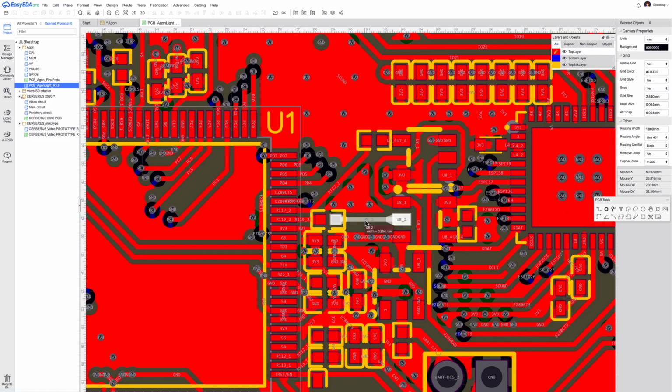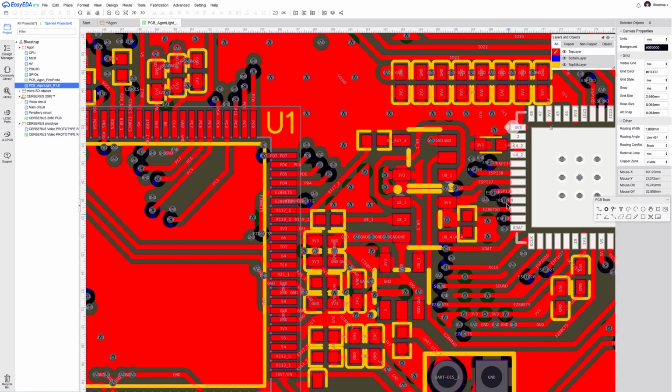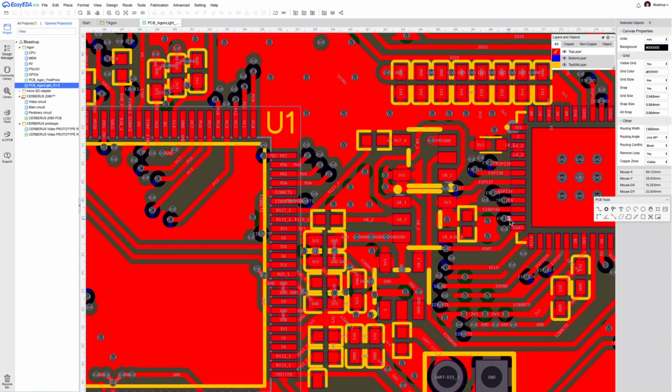This prevents crosstalk. It prevents any field fringes that are beyond the two sides from interfering with this line, that is the protected line. And on the other side, I couldn't go too far in the protection because the pins here are very close together. I need to use this pin for something else. But I put vias on them very close to the pin, so that these lines are as short as possible. And then I put a ground via here and a VCC via here to insulate this line.